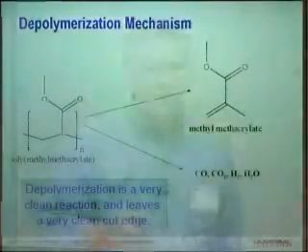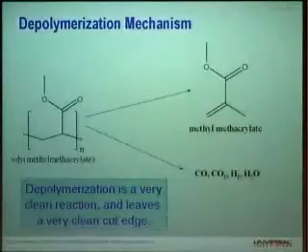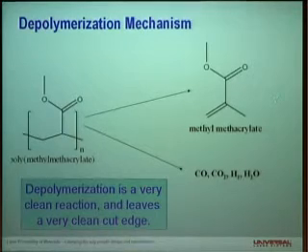When you heat this acrylic up by applying a laser beam, it goes through a depolymerization mechanism, which just means it started out as methacrylate and goes through a reaction process to build up these long chains. When it decomposes, it's just breaking back down into this methacrylate monomer, which is up here, which is a liquid at standard temperature and pressure.